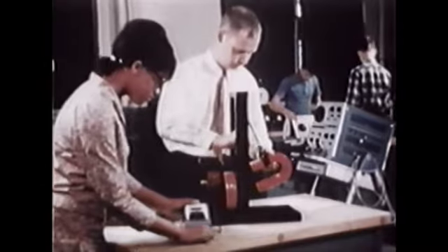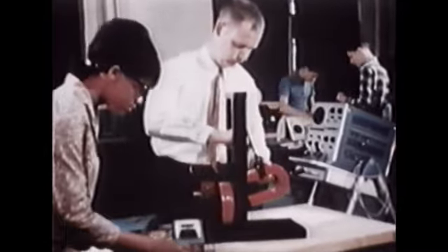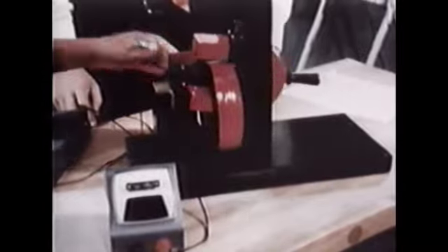To make this principle more evident, let's connect the voltmeter to a coil with hundreds of turns. This time we'll pass the magnet through the coil, for it makes no difference if the field or the coil is moving. You will notice there's an even greater deflection of the voltmeter because the total voltage is the sum of the voltages induced in each of the hundreds of coil turns.